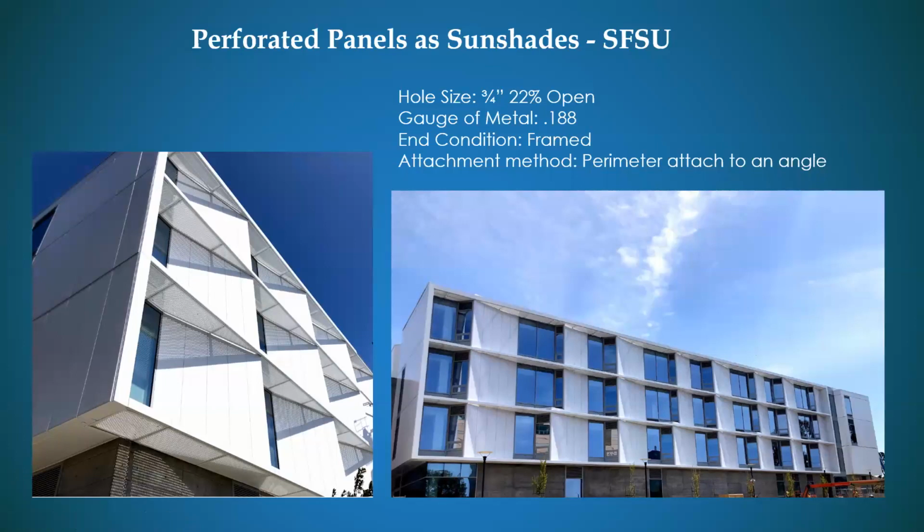Yeah, I guess one of our strong points as a manufacturer is the ability to help out with design and engineering. Design assist should be a big part of any good manufacturer. And in this particular case, there were some big spans that we were concerned about, and we had to incorporate some extra members coming off the building to reduce the span of these panels.